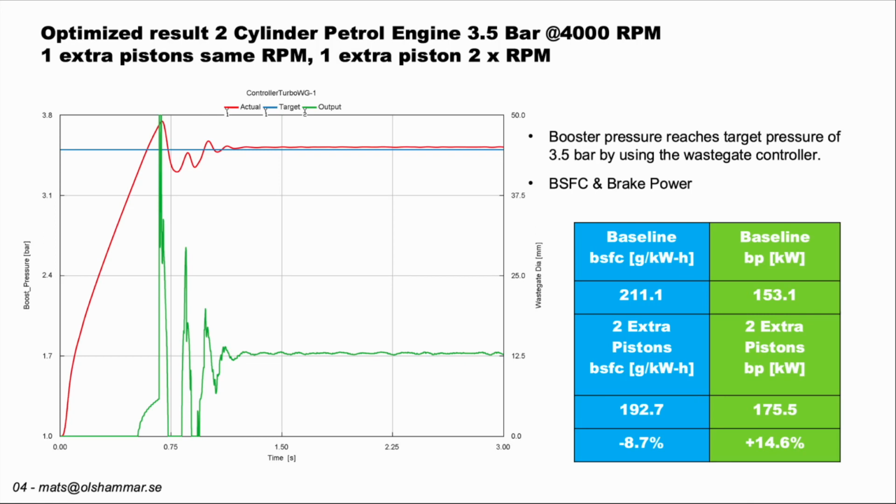But it's not as good as the other engine where we had two exhaust pistons moving at the same RPM. So this is a more complex solution, and it doesn't give us any more benefit than the other solution with two extra exhaust pistons moving at the same RPM. And we also had the one with only one exhaust piston, and that gave just as good result. So this is a dead end, I think.